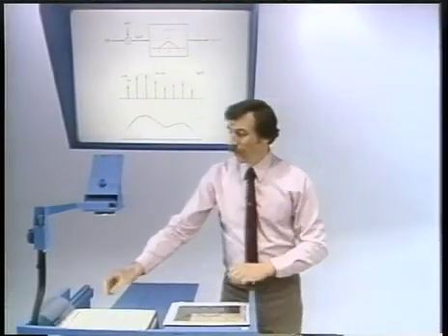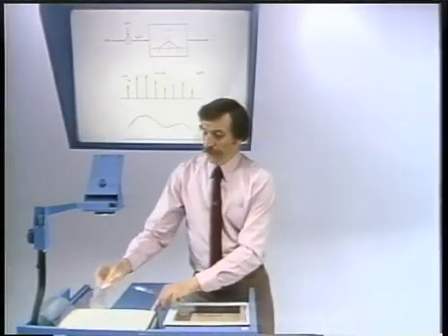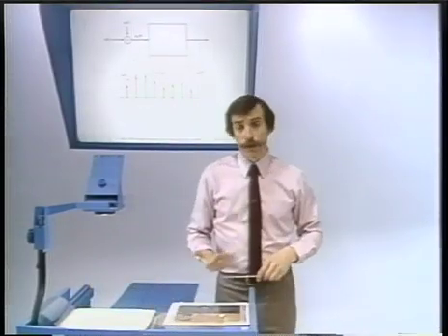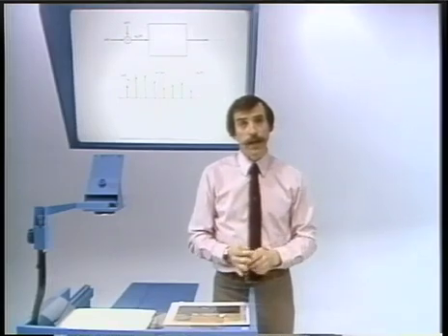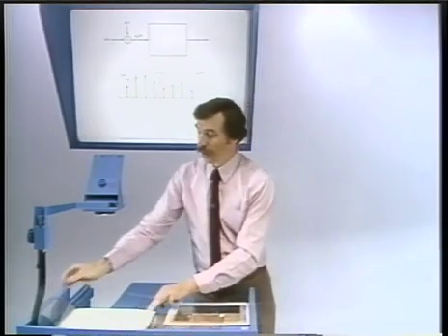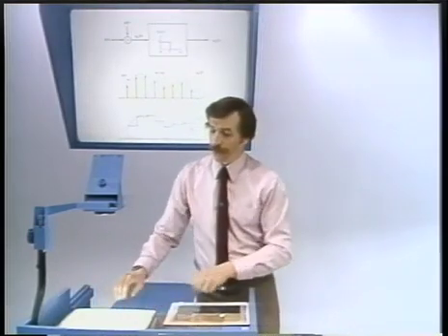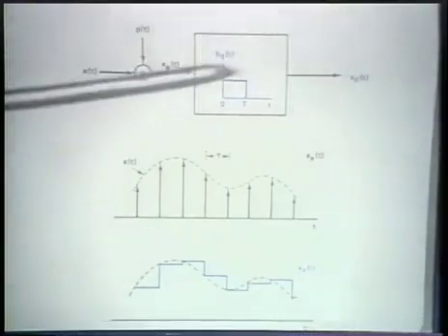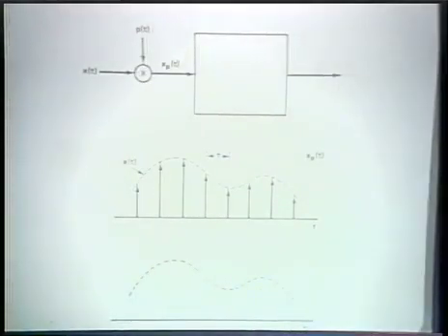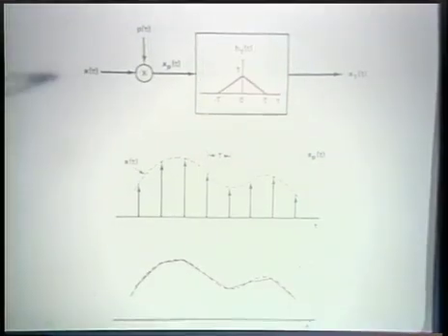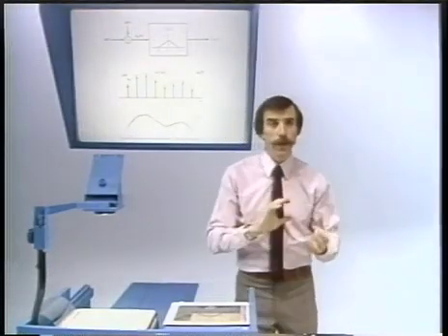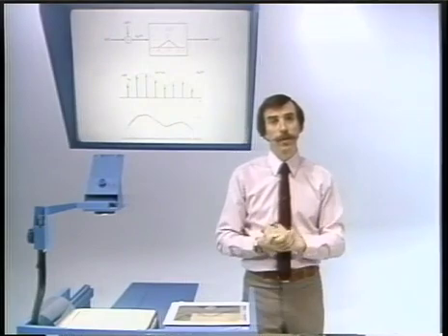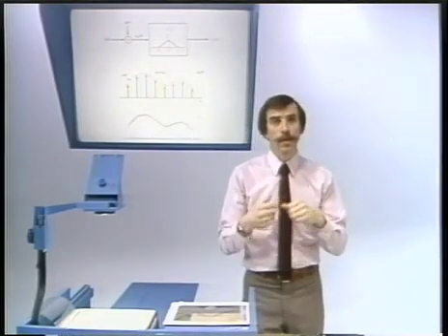Okay, so what we have then is several other kinds of interpolation which fit within the same context as exact band-limited interpolation, one being interpolation in the time domain with an impulse response which is a rectangle, the second being interpolation in the time domain with an impulse response which is a triangle. And in fact, it's interesting to also look at the relationship between that and band-limited interpolation,